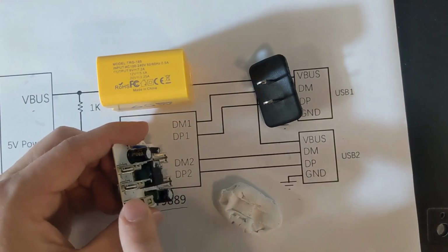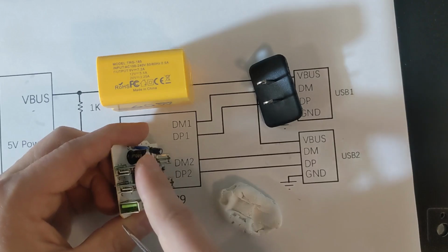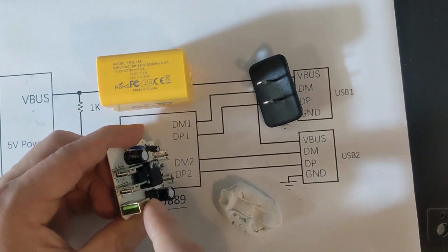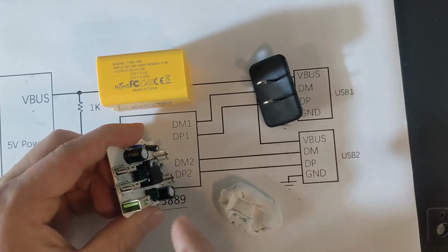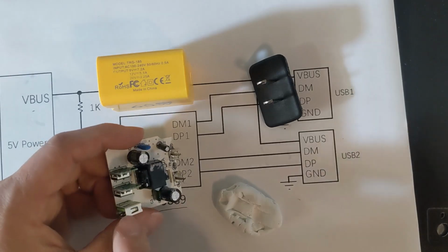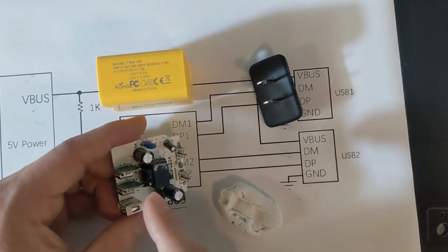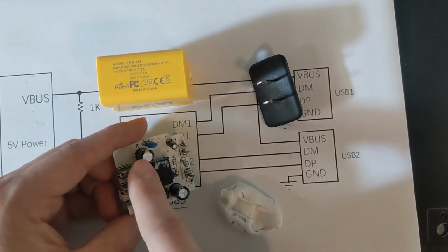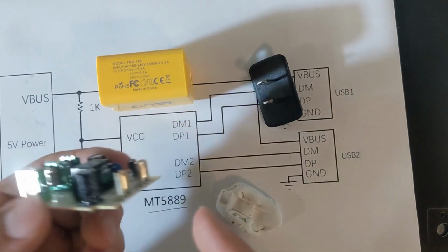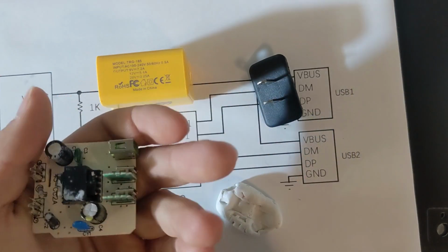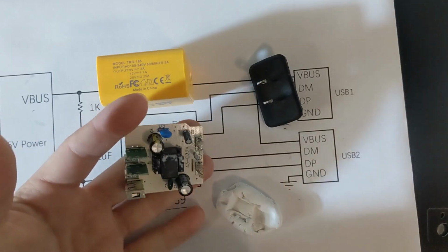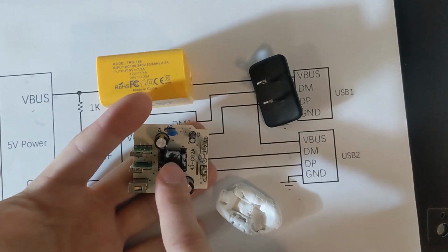Which means they have to be at 5, because if these were to negotiate a different voltage and you plugged this in, you would fry whatever else is getting plugged into this. If that device only supports legacy charging at 5 volts and you plug it in, and these had negotiated something else, then your voltage is wrong and you can fry it. So that default has to start at 5. So these can never go any higher than 5.